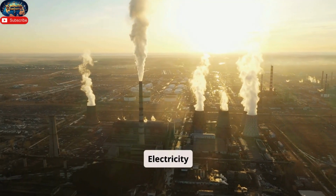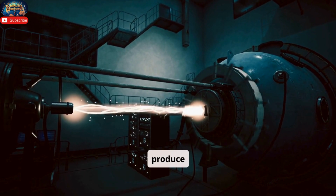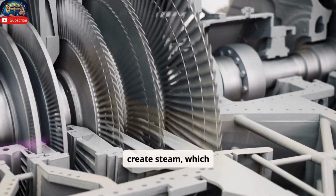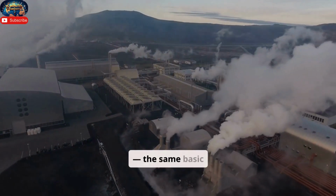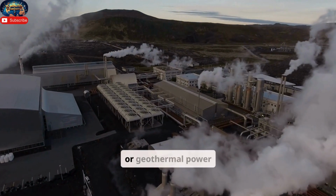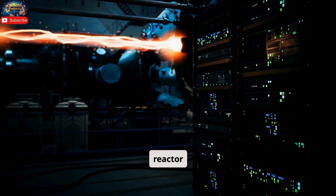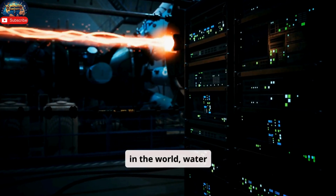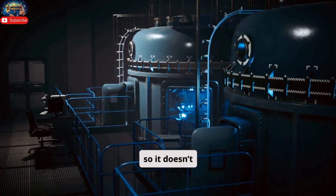Turning heat into electricity. The heat generated by fission doesn't directly produce electricity. Instead, it's used to create steam, which drives a turbine connected to a generator, the same basic principle that underlies coal, gas, or geothermal power plants. In a pressurized water reactor, PWR, the most common type in the world, water flows through the reactor core under high pressure so it doesn't boil.